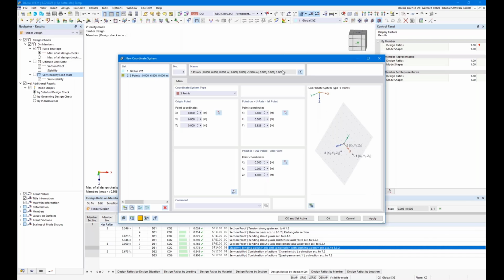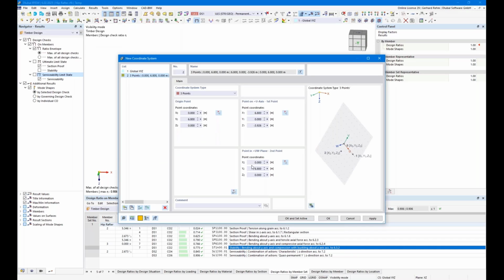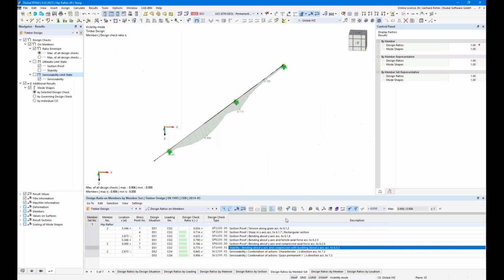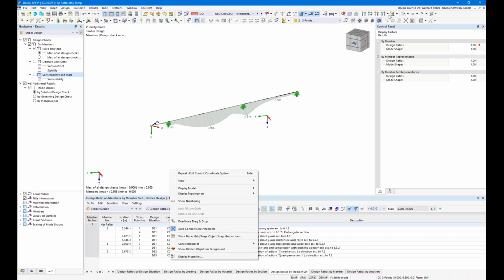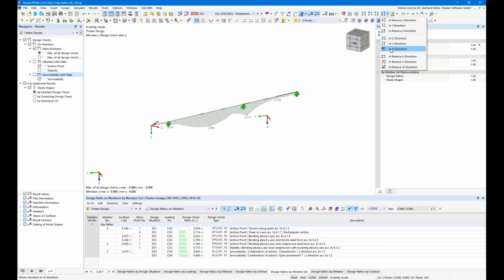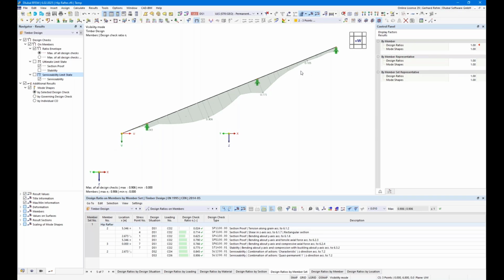The U-axis is defined by this point, and the plane is defined here. We change the coordinates easily, and this one should be at the 0 coordinate. Okay, and we see we have this user-defined coordinate system. Now I'm able to check the view directly in W direction, and that helps me to get the full length. All right.